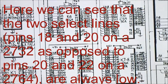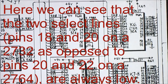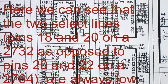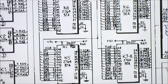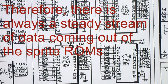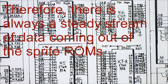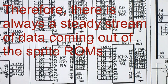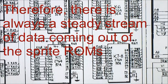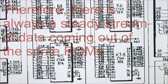Alright, I just wanted to really quick point this out. I'm looking at the Gottlieb Qbert schematic, and those are the 4 ROMs at the bottom of the board. Now the Gottlieb Qbert board uses 2764s there, but you can see in the bottom right hand corner of each chip that chip enable is held low. So as soon as these things are addressed, they're dumping data out. So that is correct. The bootleg is following what the Gottlieb board is doing.